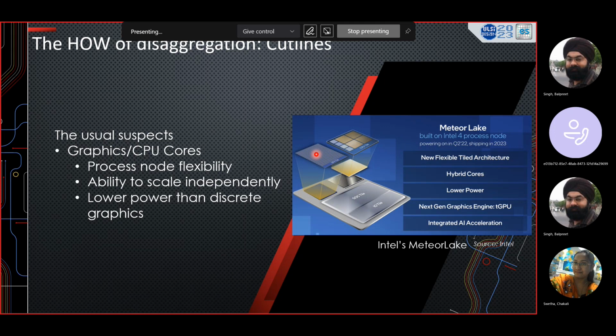It's some order, but that order is what it needs to do these two tests to get the answer. So, for example, one of the technologies that I'm going to talk about today is UCIe, the Universal Chiplet Interconnect Express. That is an open source specification that has been donated by Intel last year. Even that has a PHY. It's a high frequency and very high bandwidth PHY, which requires a SerDes. So it's hard to get around that problem.